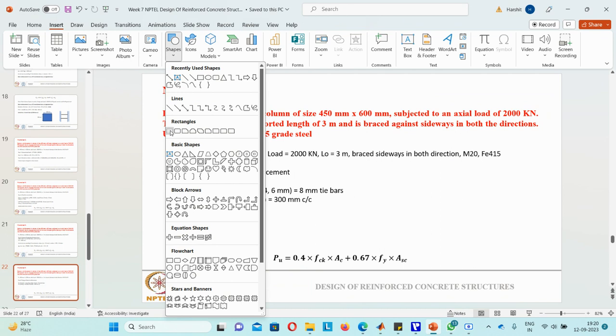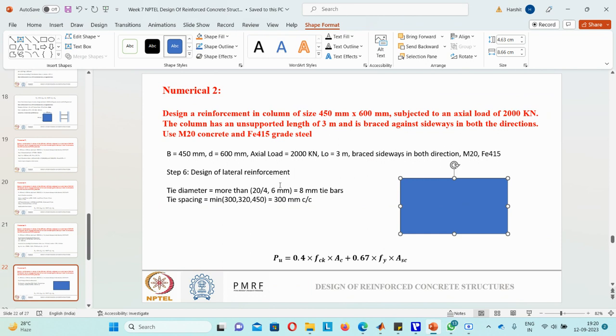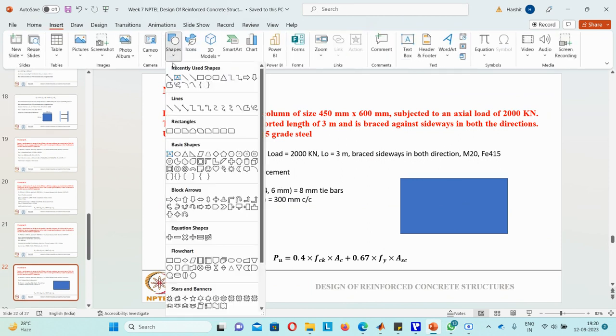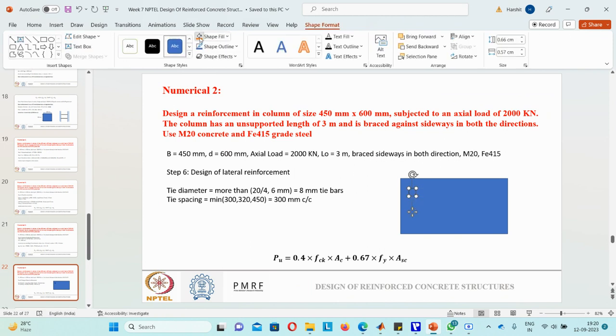Now if you see how this will appear, since we have provided 8 reinforcement bars in this case, suppose this is my top view of the section. Now how can I place the rebars? So suppose these are my rebars. I can position the rebar with some certain cover from both sides. One rebar can come here, one here, another like here, the fourth like here, the fifth here in between, the sixth here at the center.